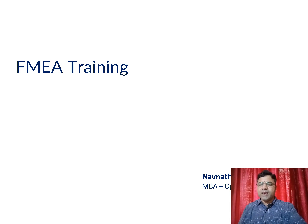Friends, today we are going to learn about FMEA. FMEA means Failure Mode Effect Analysis. This is nothing but to identify risk in our process before new process implementation or a new project. Mostly this activity is carried out in the project phase to avoid future failure modes in the product. This is a very important methodology used in quality control to address future risk in the process.